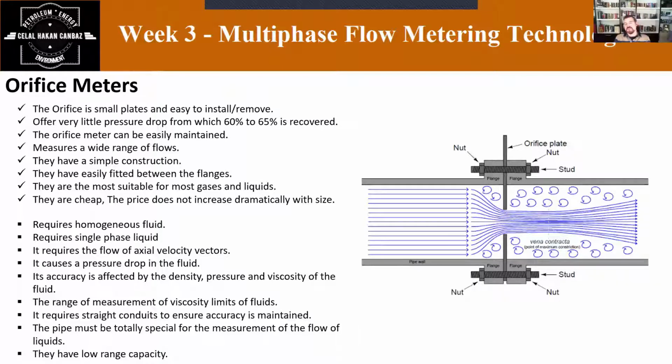Okay. The orifice meters, these instruments are one of the well-known ones, actually. And they are cheap ones, because being cheap, companies, especially mid-range companies, prefer this too much. So this is an instrument that records the flow rate of gas, especially. We are using this for gas measurements through a pipeline. The flow rate is calculated from the pressure differential created by the fluid passing through an orifice of a particular size, of course, and other parameters such as static pressure, temperature, density of the fluid, and of course the size of the pipe.